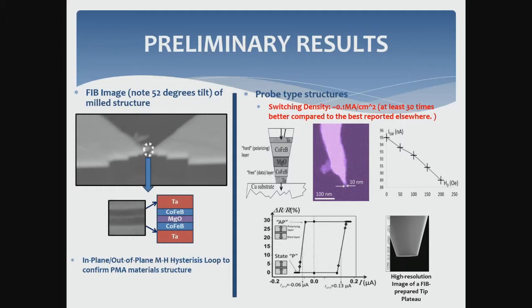To further exemplify the importance of the tantalum, once again, this acts as a protection barrier but allows proper contact to the metallic substrate. Now, we also applied external fields, in which we showed from the phenomenological equation that we can further reduce the switching currents by applying an external field. And as you can see over here, the switching current scales down with the applied field.